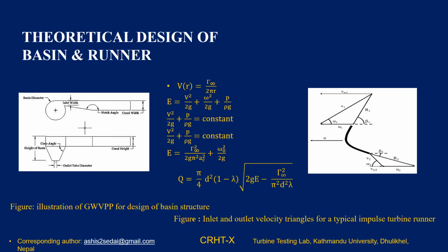For our research, we firstly studied the theoretical design of basin and runner. We designed our prototype using the same concept. So the first equation that we see is the tangential velocity distribution equation, and the second equation is the Bernoulli equation, and we use these equations to identify the equation for developing our basin structures.